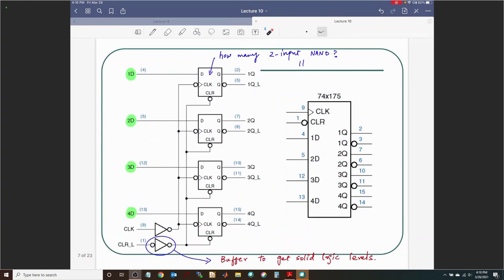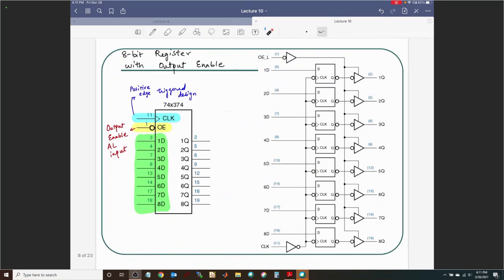This guy? Right. So this is a 4-bit register, in which you have the option of using the synchronous clear, positive edge designed register, and outputs are both in true form and complemented form. Yeah, clear too. Yes. And then this guy says, all right, I'm not going to worry about the clear. I'm going to make this sort of a connecting multiple outputs together exercise, right?